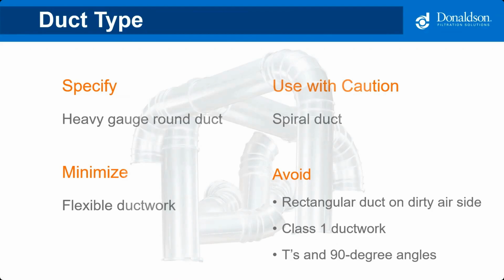And be aware that flexible duct requires significantly more energy than traditional hard ducting, so we recommend really minimizing the use of flex duct as much as possible. And then lastly, you'll want to avoid T's and 90-degree angles as much as possible.